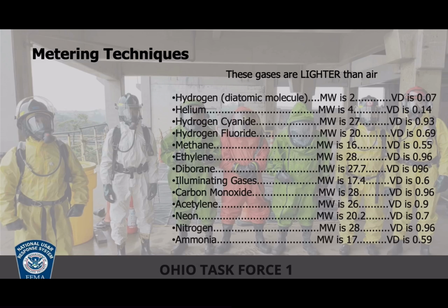So where would we find carbon monoxide? It's marginally lighter than air, but because it's marginally lighter than air, kind of like how hydrogen cyanide is, they're going to be very susceptible to air currents. So wherever we find air moving or air collecting, turbulent airflow, look in the higher headspace of that area, and that's where you're likely to find your carbon monoxide.